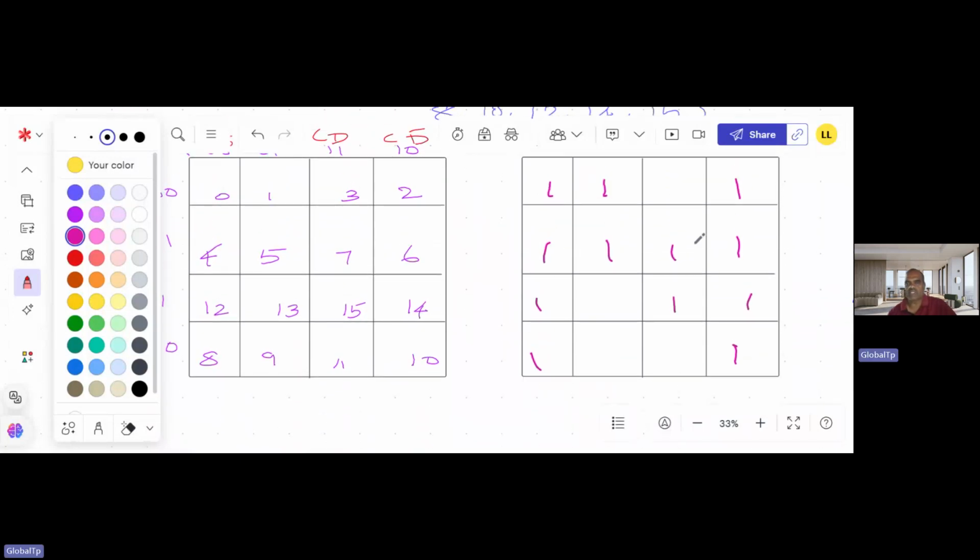After doing this, first you need to check whether 8 numbers can be joined together to form an octet. In the Karnaugh map, 3 possibilities are available. Joining of 8 ones. If not possible, then you have to check 4 ones, and then you go to 2 ones, and then you form a single 1.